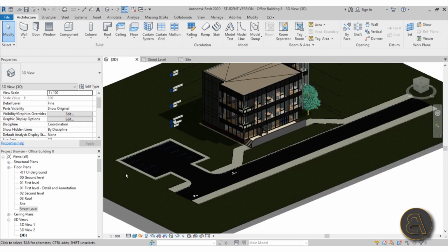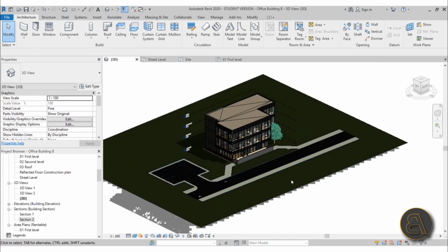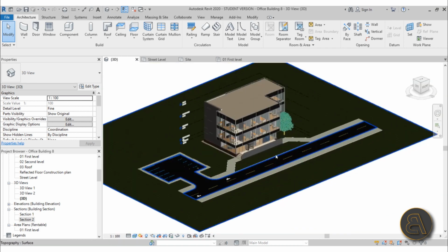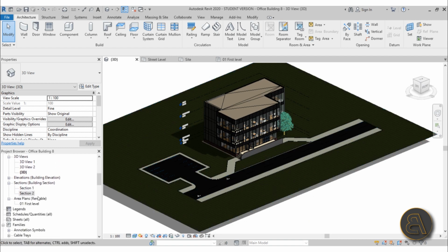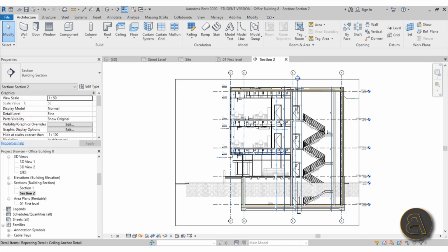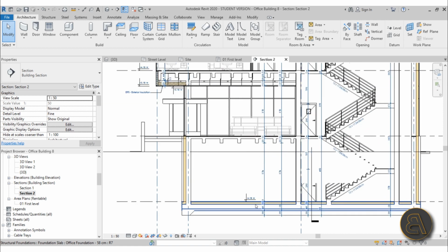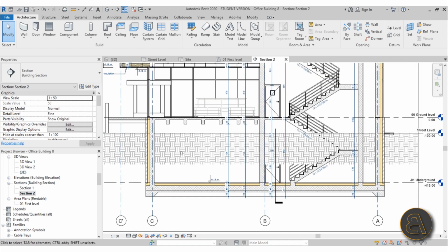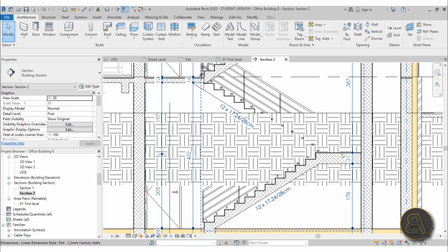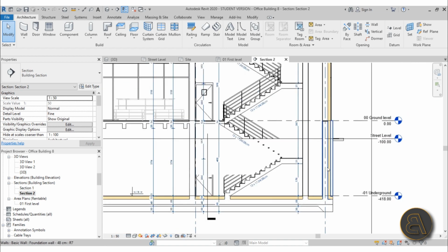and parking. Now, one more thing that I should definitely mention when talking about the site, and that's the building pad. So once we have created this topography all the way around our building, if I go here into the project browser and open up one of the sections, let's go with maybe section 2, that's the one where we added most detail, you're going to notice that now we have our terrain that's going through our building, and that's definitely not something that we want to have.